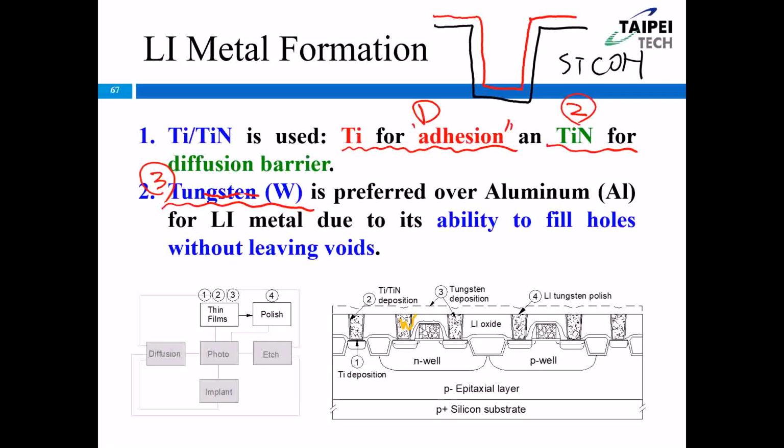Pure metal is easy to oxidize, and it oxidizes with the outside, meaning the oxygen atoms will go to the Ti and form TiO bonds, which helps it have better adhesion. That's why adhesion layers are pure metals. So today we use the Ti for the adhesion layer because Ti can react with the oxygen here to form the TiO bond. That's the reason the first processing step will be Ti, a very thin layer.